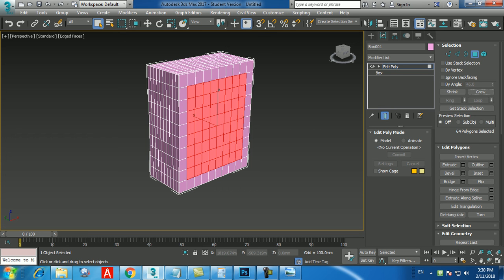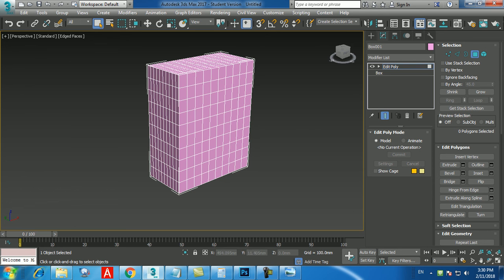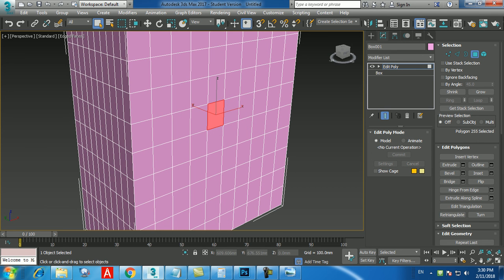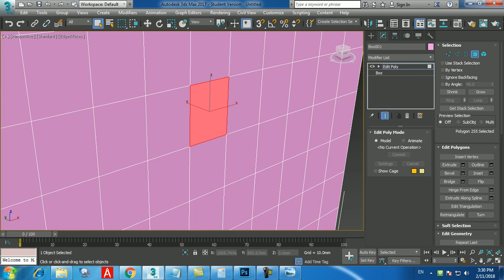If you want to cut the polygon diagonal shape, you mean this part, right? Then you have to manually select it. That you should not do when you are in poly, because when you cut a diagonal shape, it won't be a polygon anymore, it will become a triangle. If it is a triangle, then you're no more inside poly creation, you are inside mesh creation.